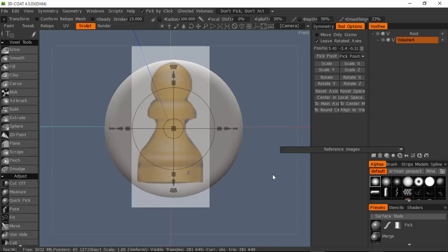If I was going to do a side image to go with this, I would want to have them in layer software where I can make sure that my images are exactly the same dimensions and my center points of the object that I'm tracing are the same, so that it's very easy for me to align them in here. We'll talk about a side, a Y reference image later, but for this tutorial the pawn doesn't need two images, it just needs the one.